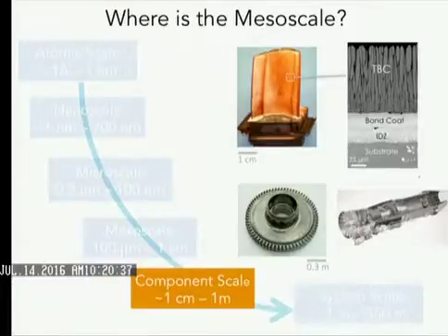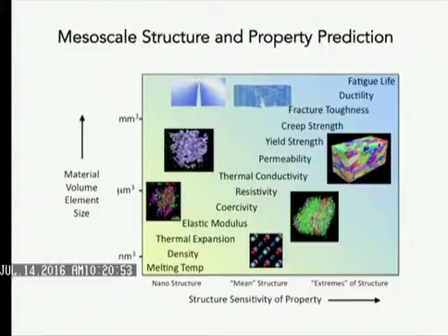And so I show here again that engine from earlier. I'm going to talk a little bit about some of the stuff in the hot section just as an example. This is a turbine disc, so this is probably the most safety critical thing in the engine. If you lose it, you lose probably the plane in most instances. Okay, so coming back to the mesoscale, typically what we have to do is sort of account for all of that structure.